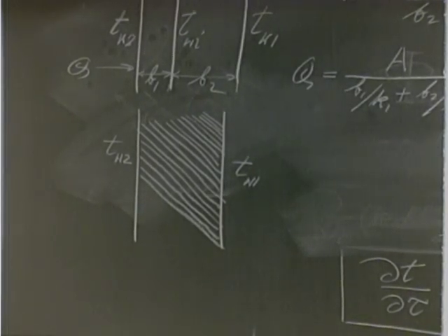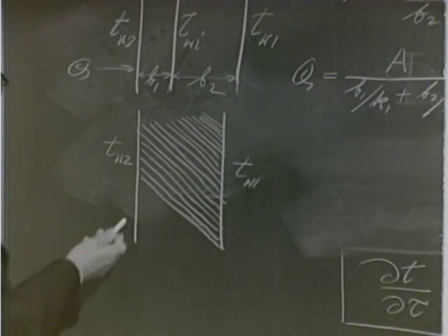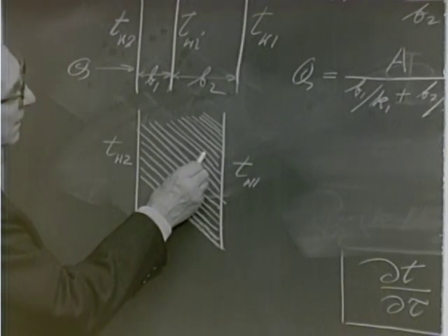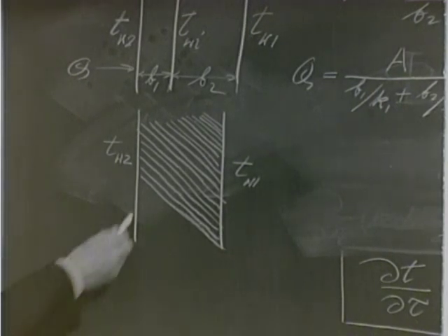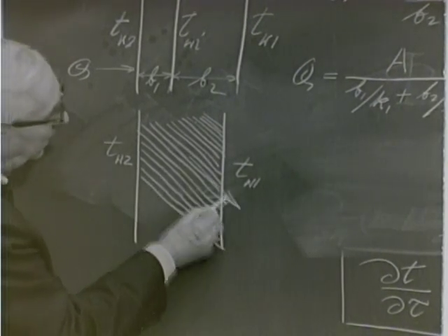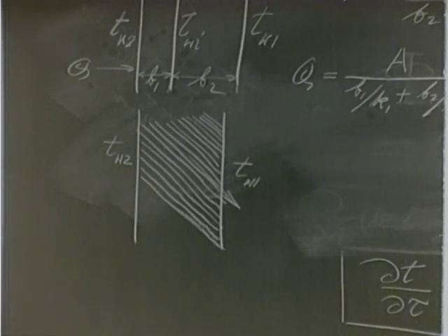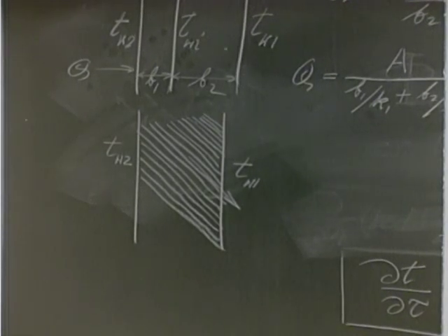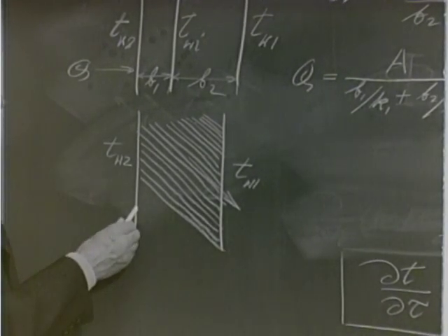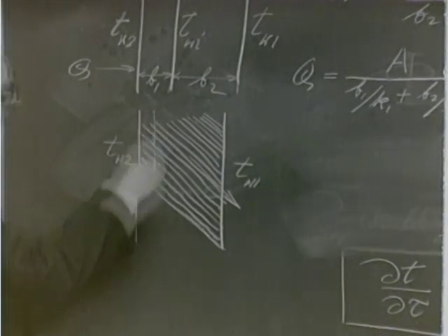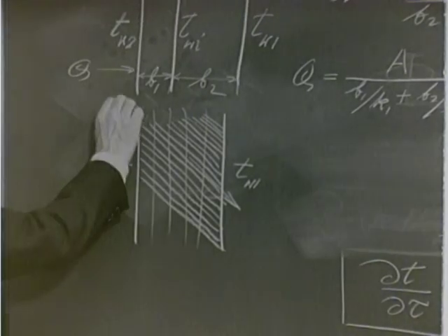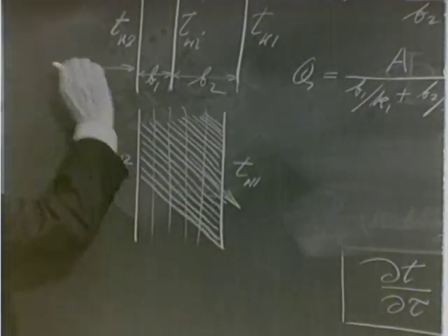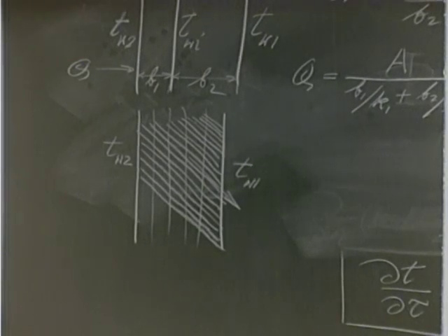Question: in which direction does the heat now flow? Obviously, there can be no heat conduction crossing the material which has a thermal conductivity of 0, which doesn't conduct at all. So this means really the heat flow has to go down in the various metal strips, which is a situation which we have not looked at before. You see, isothermal surfaces will still obviously be planes parallel to the surfaces, but now the heat flow lines are not normal to the isothermal surfaces, they are somewhat inclined.